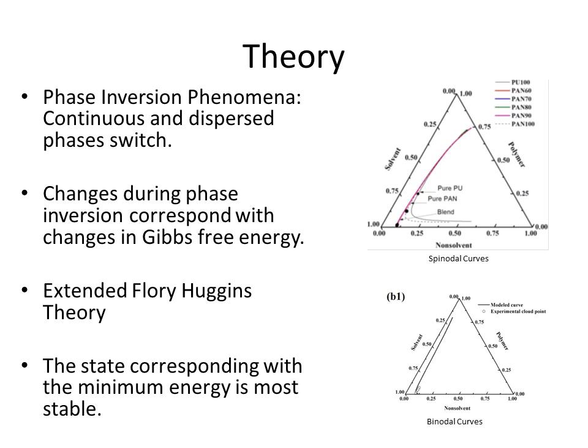The spinodal curve signifies the limit of stability and is important in many membrane-forming models. So on the right here, you can see we have a spinodal curve, and then below that we have a binodal curve. And these phase diagrams are important in helping us understand the system, and with the system properties we see, we can actually predict properties of the membranes that will be formed from these polymeric mixtures.